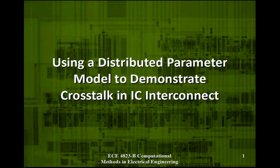The problem I chose for my project is the issue of crosstalk between IC interconnect. This occurs because ICs are fabricated on such a small scale that wires in close proximity exhibit capacitance. This capacitance allows signals to be transmitted between wires erroneously. To understand this behavior, I set up a model that produces a pair of coupled PDEs, and then solve these PDEs under various conditions.